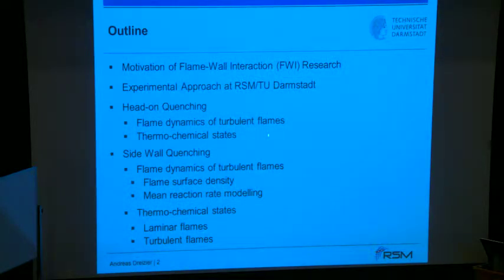And so you will see here flame dynamics as well as some idea about thermochemical states going clearly beyond only heat transfer. And the sidewall quenching, which is now preferred by my side to investigate, we will see how you can make use of this kind of imaging to come up with a mean reaction rate deduced from that data.